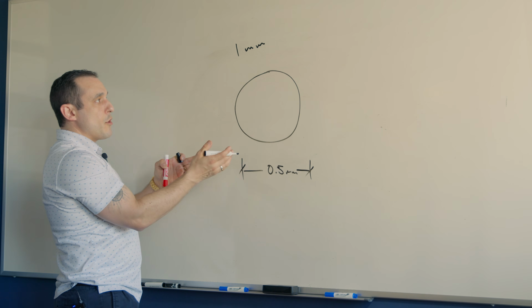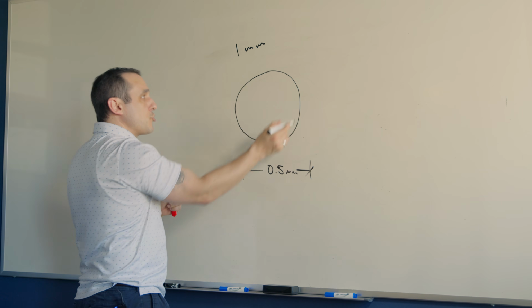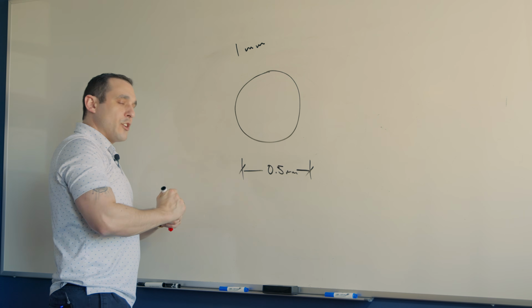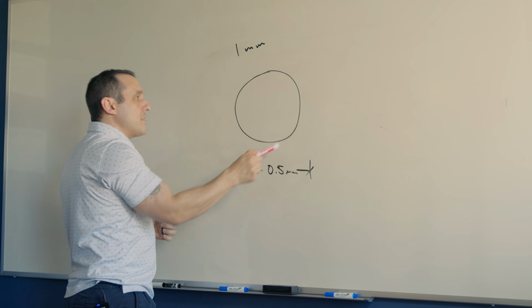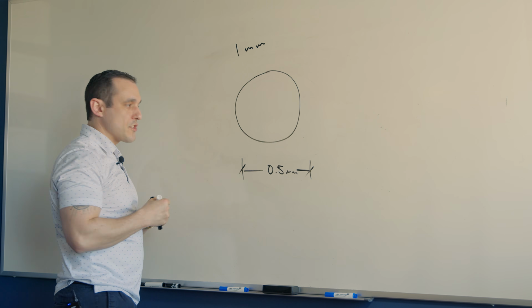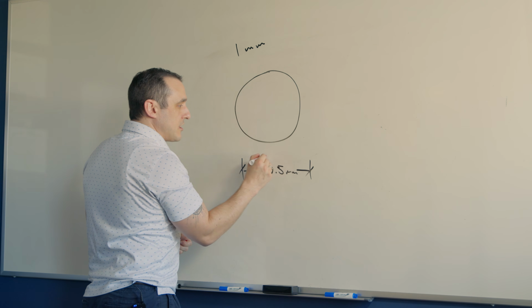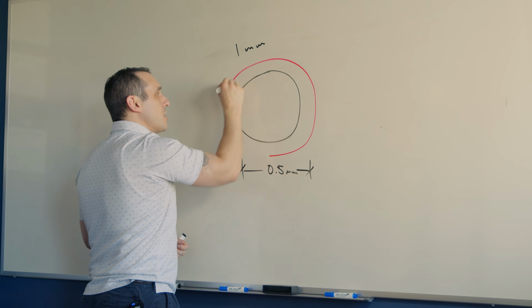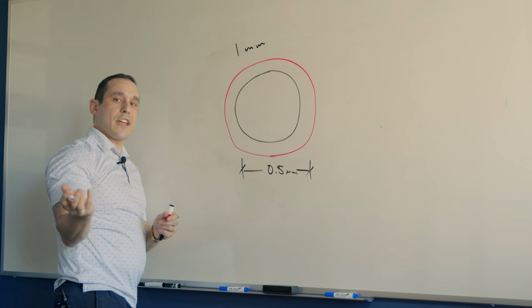Now, this is the exposed copper, and if this is the actual size of the copper pad, in order to ensure that we always have this much copper exposed for soldering, we would then apply a little bit of solder mask expansion around this pad in our CAD tool.